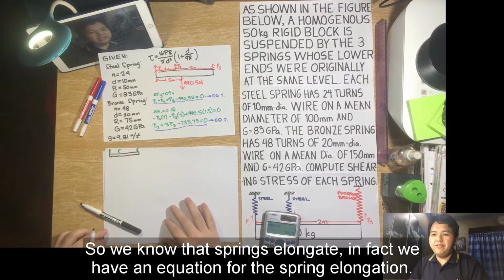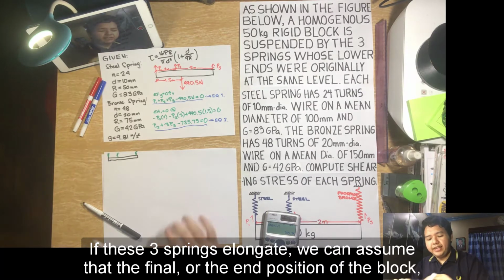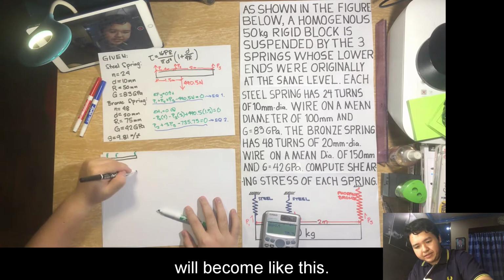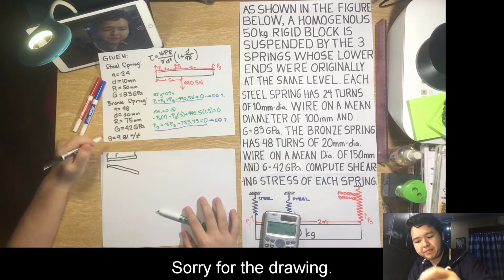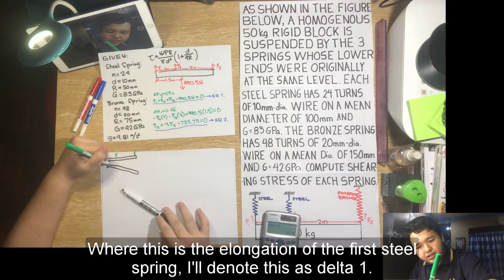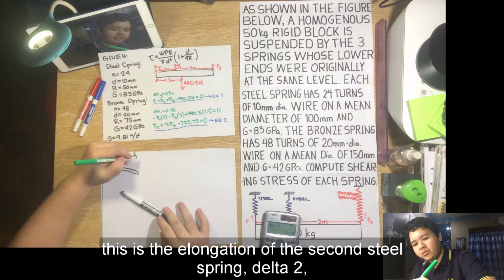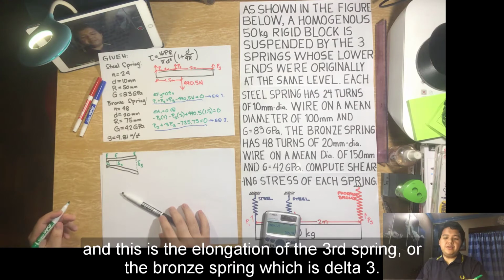So we know that springs elongate. In fact, we have an equation for the spring elongation. If these 3 springs elongate, we can assume that the final or the end position of the block will become like this. Sorry for the drawing. Where this is the elongation of the first steel spring, I'll denote this as delta 1. This is the elongation of the second steel spring, delta 2. And this is the elongation of the third spring, or the bronze spring, which is delta 3.